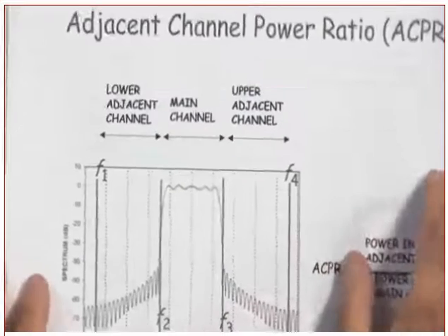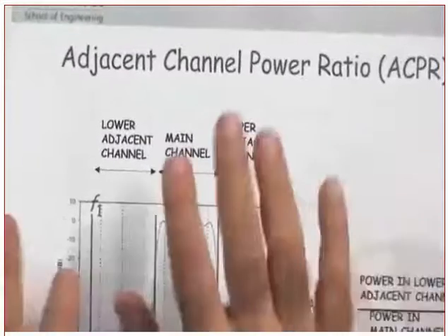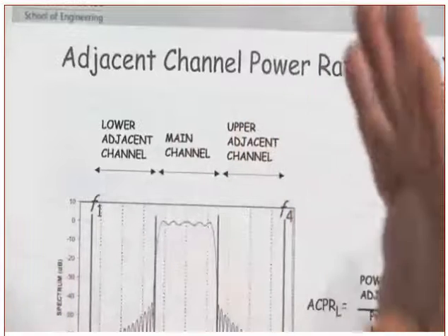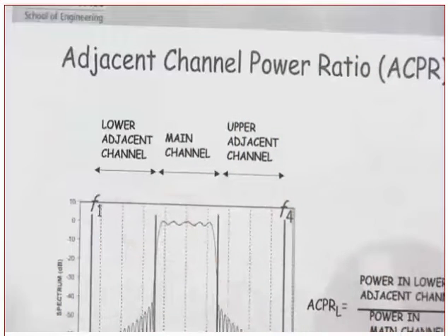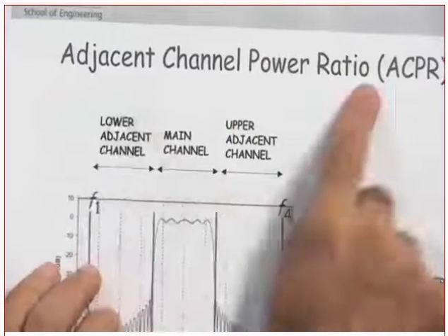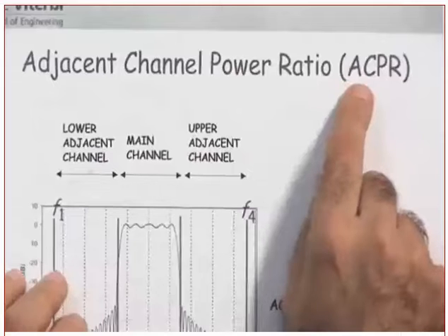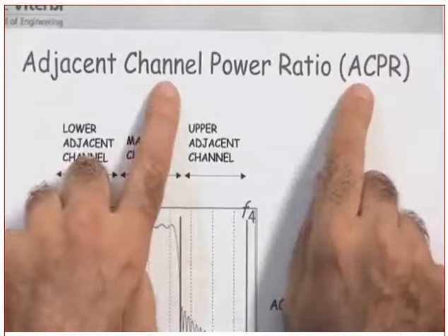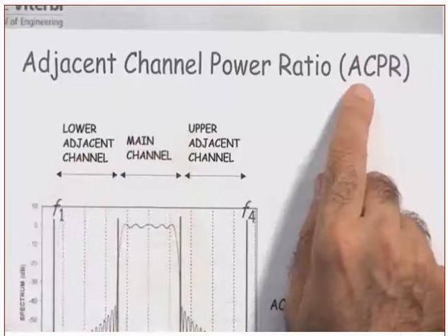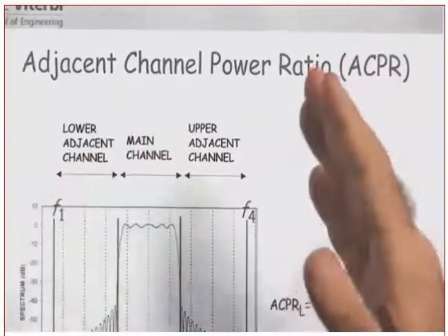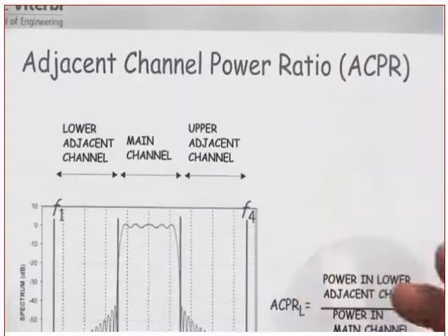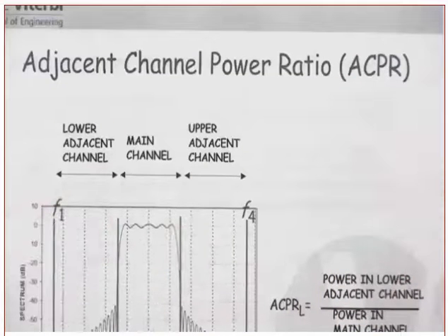Another measure for linearity, which is also used a lot, especially in the specs of standards like GSM or CDMA, is what is known as ACPR. ACPR stands for adjacent channel power ratio, which is the ratio of the desired carrier divided by the power from an adjacent channel, or vice versa, by the way. You understand what vice versa means? The answer is either in positive dBs or negative dBs. Did you get this or not?